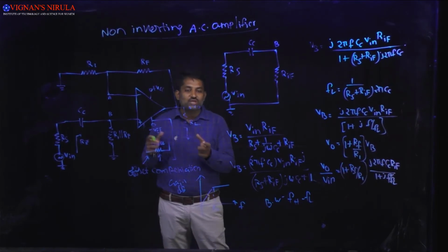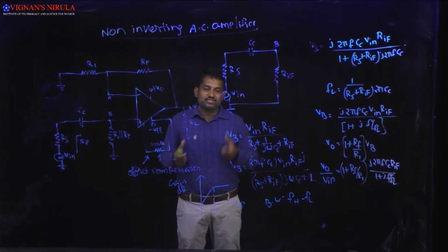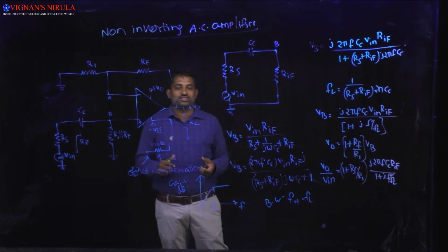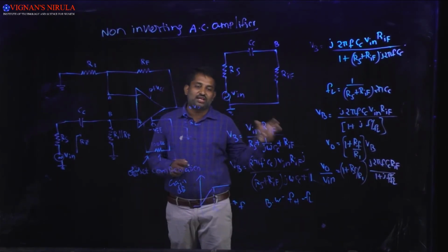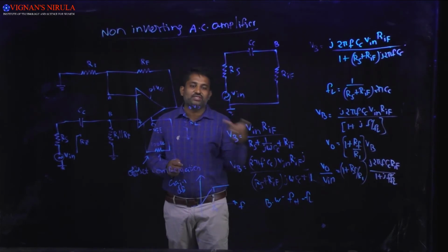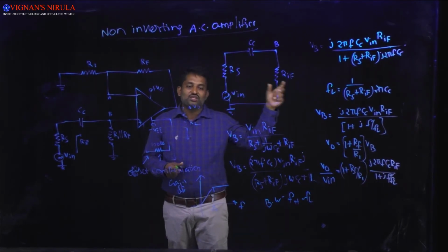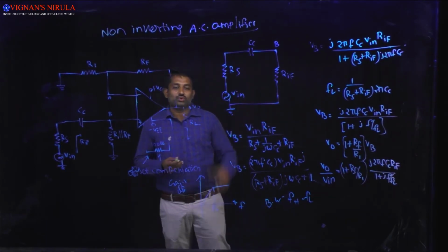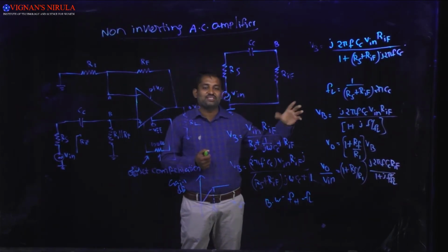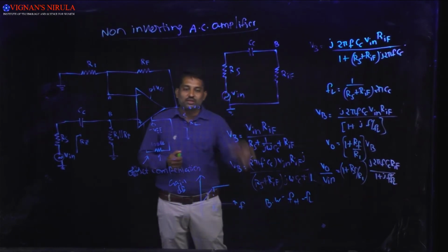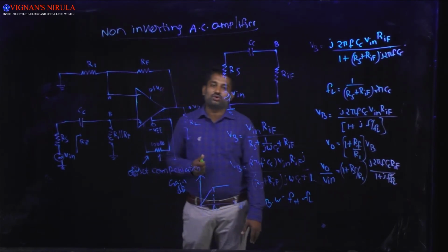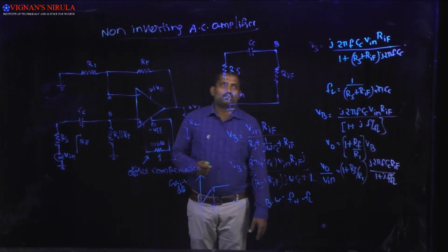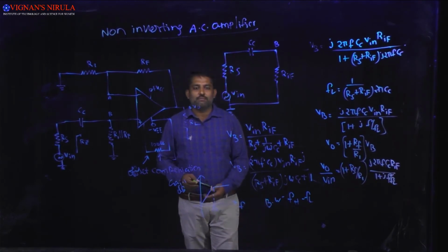The use of this compensating resistor and compensating network in both cases is to eliminate the offset errors. If you eliminate the offset errors, you will get an undistorted output. So to get an accurate output voltage value, we have to eliminate these offset errors. That's it for the AC amplifiers.